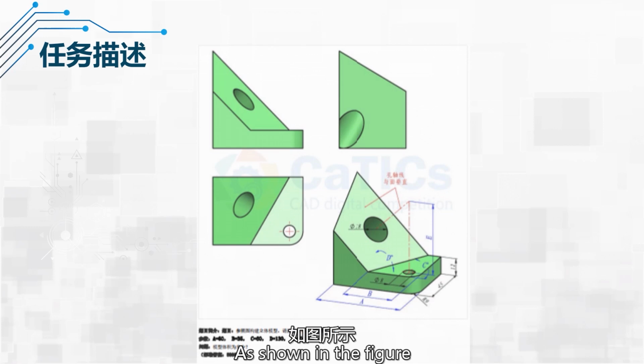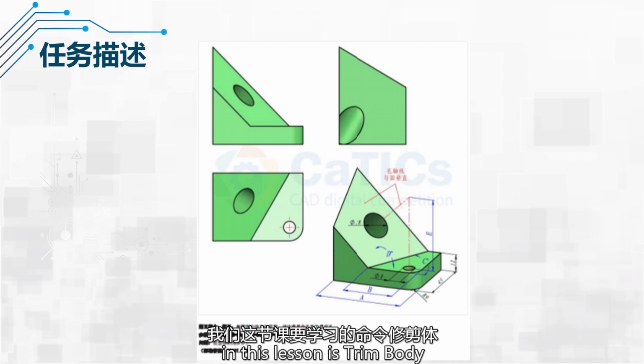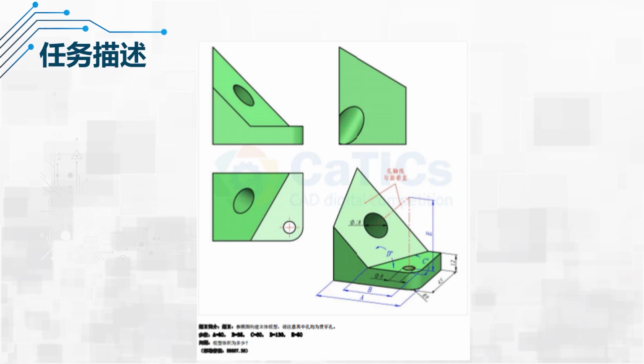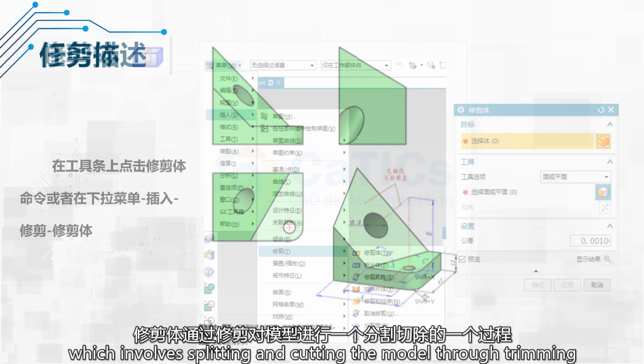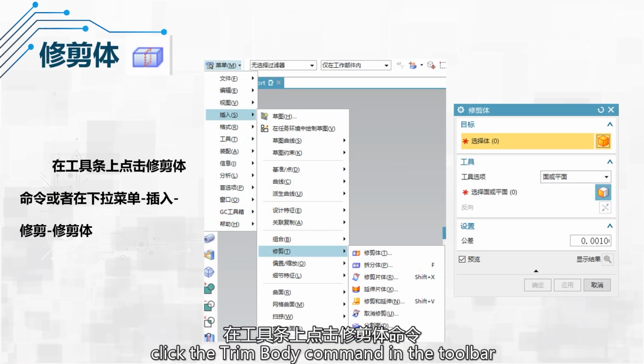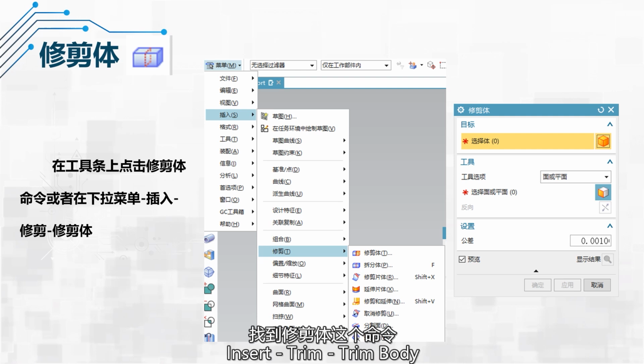As shown in the figure, this model is split and cut from a complete body. The command we will learn in this lesson is trim body, which involves splitting and cutting the model through trimming. For the trim body command, click the trim body command in the toolbar or find it under the drop-down menu Insert, Trim, Trim Body. Open the command and we see an interface.